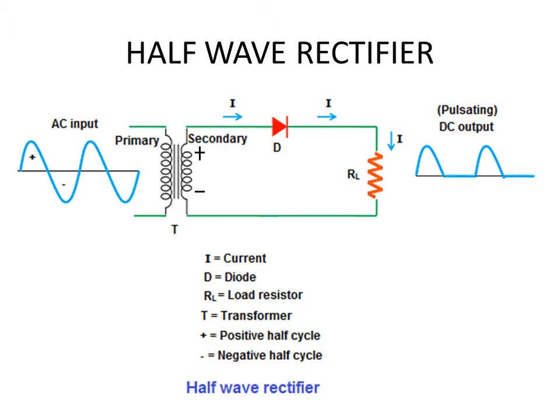During the positive half cycle, the polarity of the voltage appearing across the secondary is considered to be such that, since the secondary is actually a coil, you are measuring the output from between the two ends of the secondary winding. During the positive half cycle, the top end of the secondary winding will be positive and the bottom end will be negative.